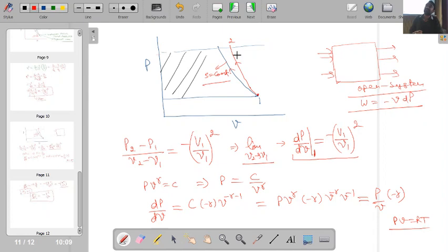So it means that the shock wave compression process is not efficient. It is less efficient than the isentropic compression process. Okay, so that's why you will not find in the majority of devices that we go for a shock wave compression process. All the devices are tried to be made equivalent to the isentropic compression process.